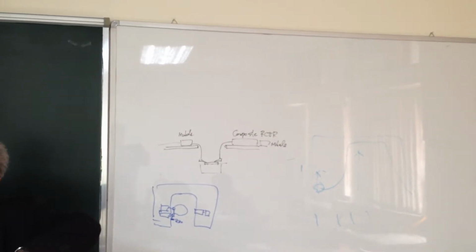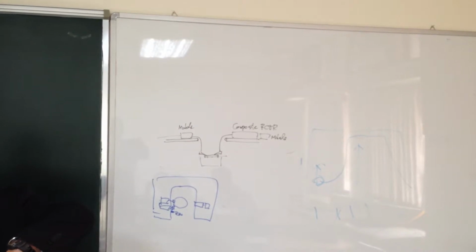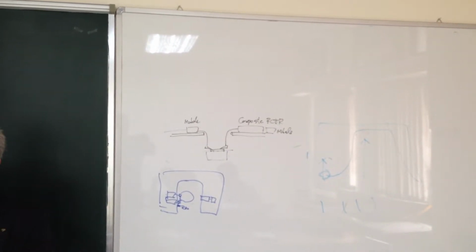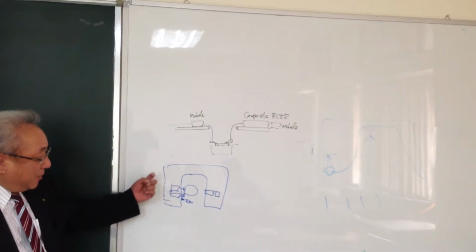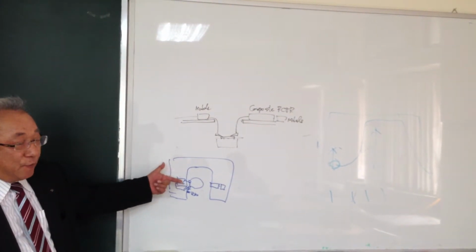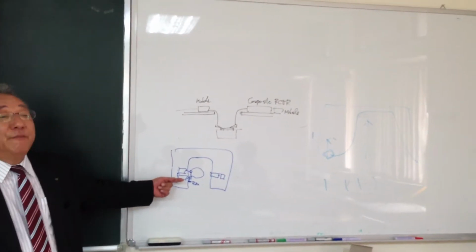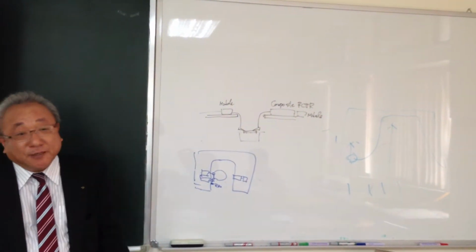And the other side, the receiver side, is moved by the positioner. Then attach. That is one idea. But we need to assume the two probes are exactly the same. One is for S parameter measurement or the calibration for the receiver side, and one is only for the termination probe tip. That's one idea.